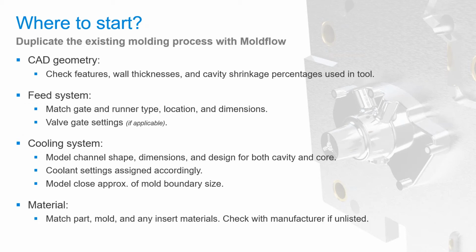And finally, modeling the mold boundary adds additional accuracy into the simulation by providing a better guesstimate of the actual mold size within Moldflow. And this is in the case of when you might not have the mold block model that you would want to import in Moldflow instead.